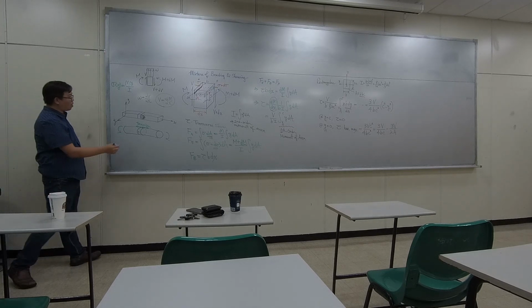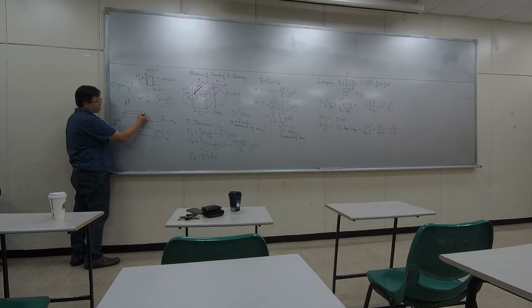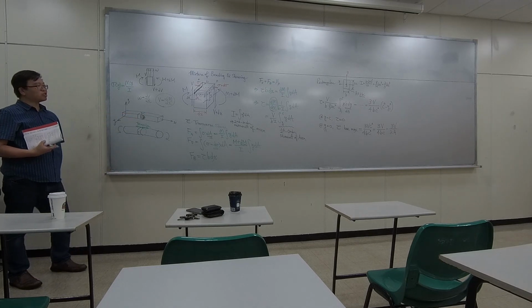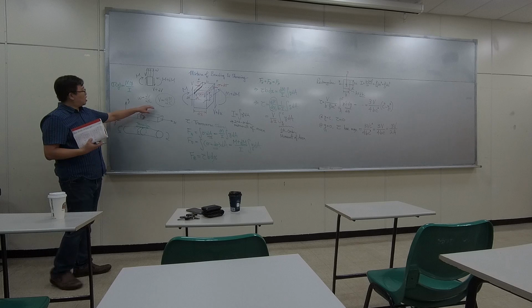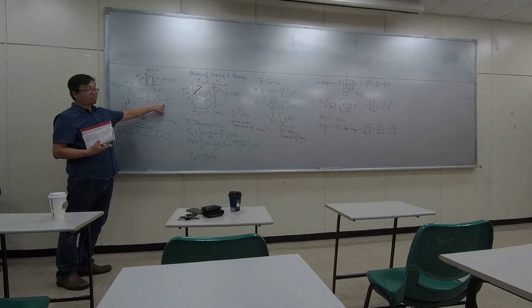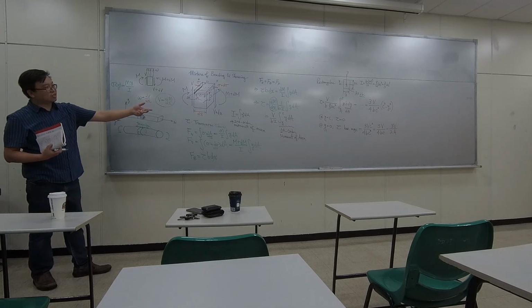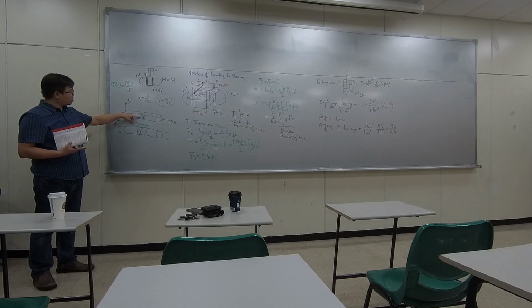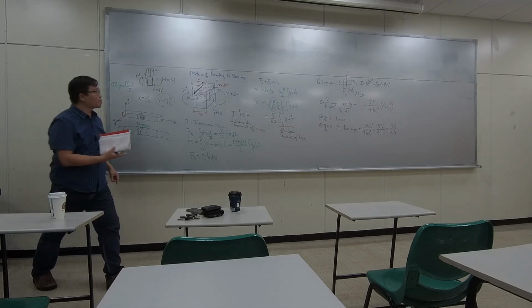That's also why at the very top we usually don't need to talk about transverse shear, no matter if you have a change of bending moment, because this remains 0 at the very top. However, if you are talking about somewhere at the neutral plane, then it's a different story.